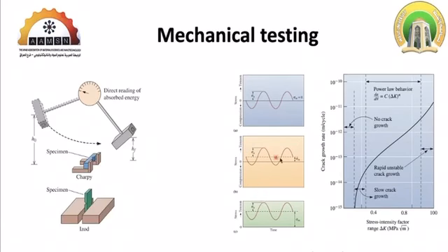So we do have a mean load, a mean stress, and then we alter the load up and down this mean load to cover the compression area, tension and compression area, or tension area only. The outcome of this test is the endurance limit, which defines the number of cycles that get the material to failure.